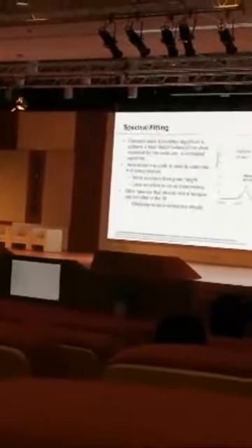So this is something which goes through an extensive process in our factory in the UK. Another important fact is that, just like in a gas chromatograph, we are not measuring the height of the peak, we are measuring the area under the peak. So that gives us more linear and repeatable results. This also helps us in eliminating cross interference. So this is one technique which we use all the time.